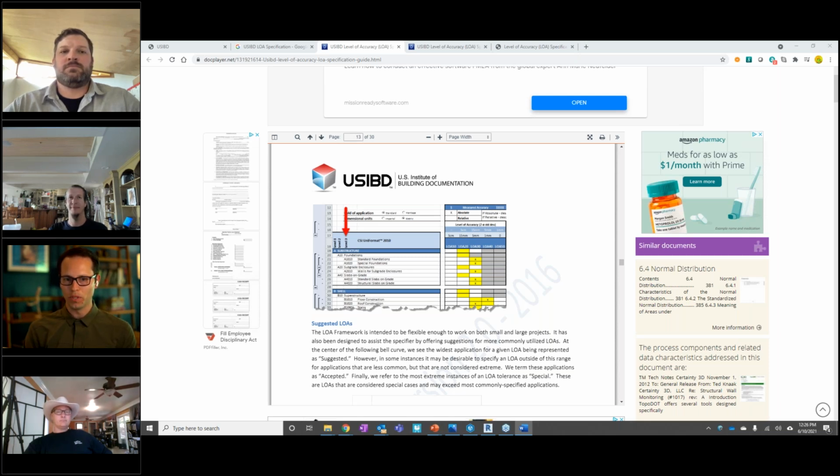So I would always encourage, at least for our industry, to use shared coordinates always to bring in point clouds. But that's challenging because when you bring in the point clouds by shared coordinates, it might be rotated, it might be not at zero. So you need to find solutions to take the coordinate system in Revit. If you move that manually and locate it, take that coordinate system and override the coordinate system of the point cloud. So from that point on, everyone on the team will bring that point cloud into the project